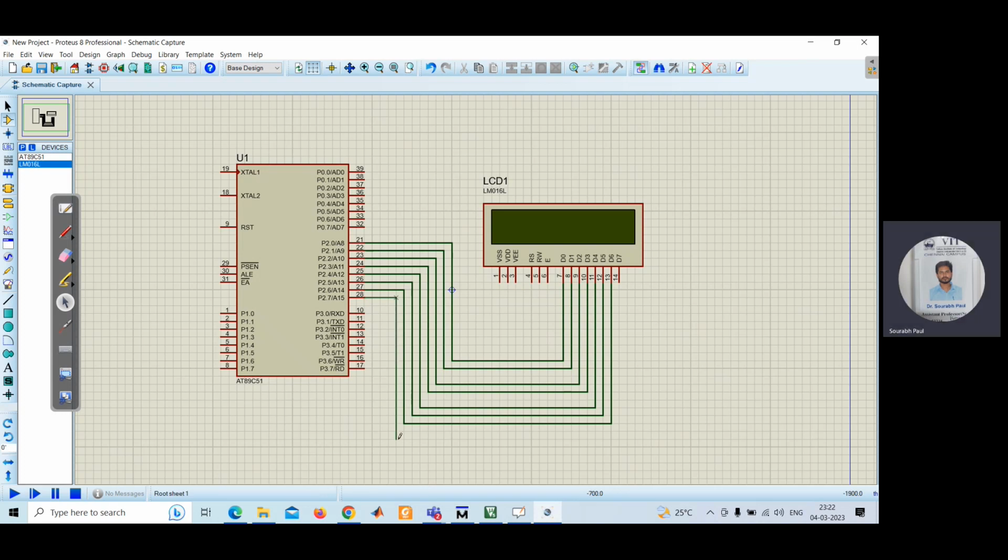So this software we are using basically to see the output. And this virtual type of connection we are making between the 8051 and LCD. Okay, so this is the data line connection I have done, and I considered port 1 pin number 0, this port number 1 pin 0, I have to connect with RS. Yeah, the program I have done this way.